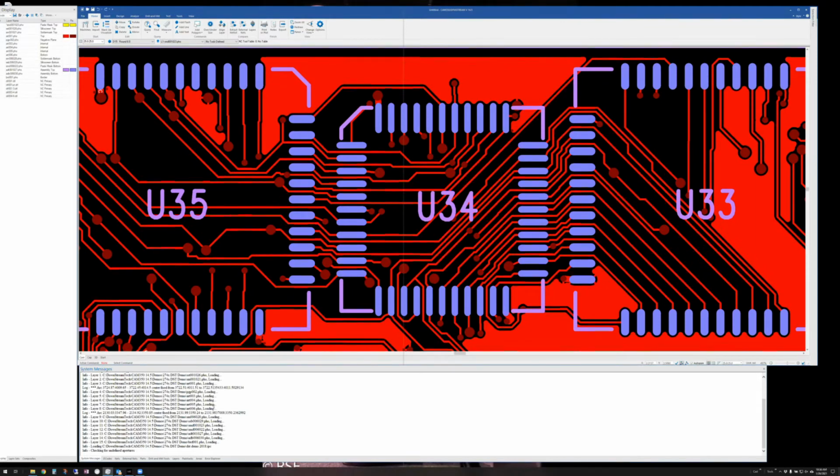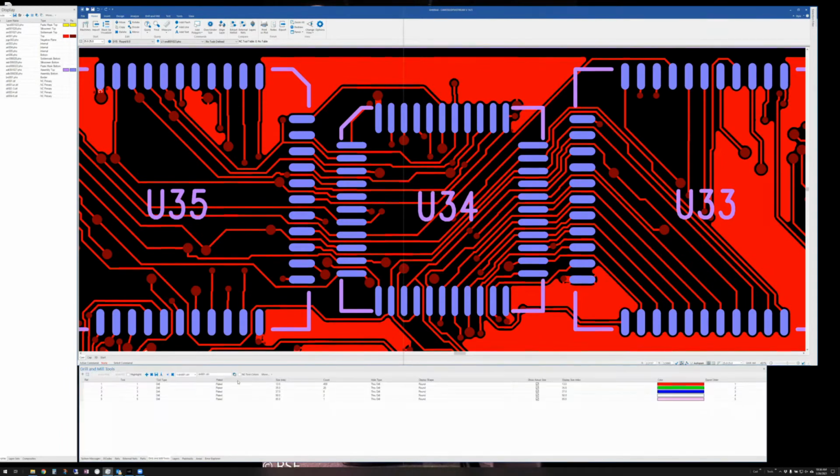It was actually its own toolbar, I think, in 12.2, but it's just part of the tables down here in this one. My drill and mill tools, again, if I wanted to change a plating characteristic of something, but since I did it at the loading stage, you'll notice that that unplated drill is already listed as unplated. Now, if I had combination on this layer, let's just say this 85 was a non-plate, I could go in here and change it to unplated. Okay.